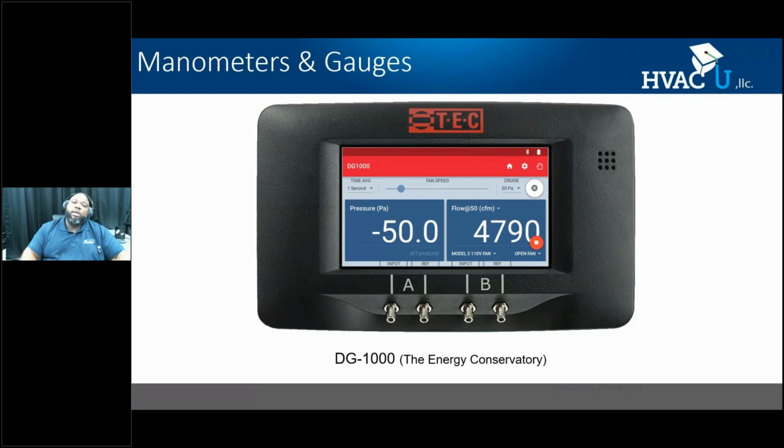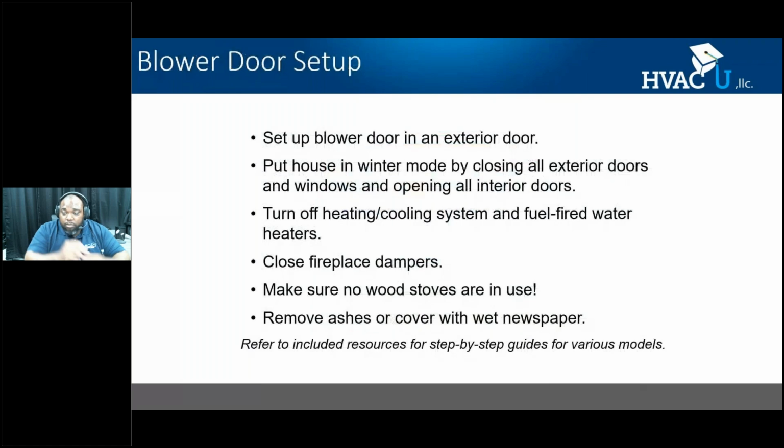The way it works, the higher the CFM number right here, the leakier the house. We take this input, or a modified version of this input, and put that into our load calculation software. Once again, this is more accurate than coming up with some type of description like loose or semi-loose or tight. We can't determine what those actual values mean without testing, so it's a much more accurate way to fine-tune your loads.